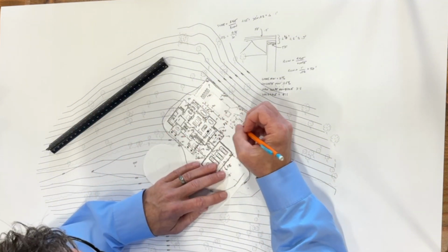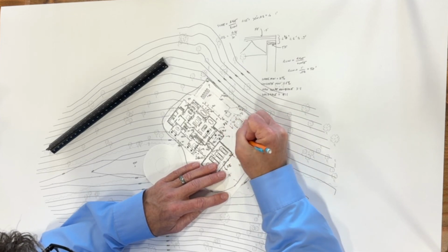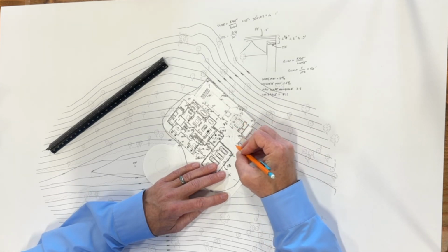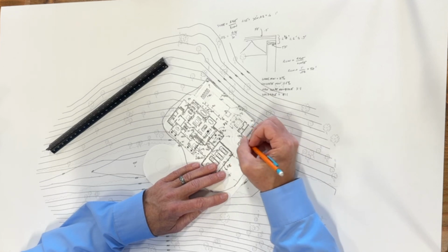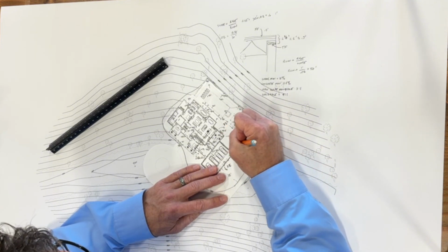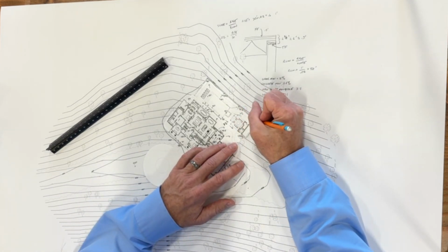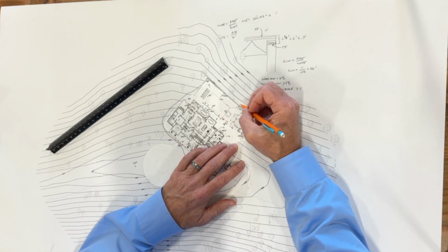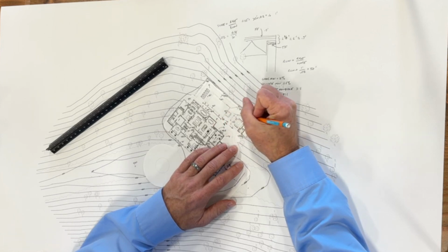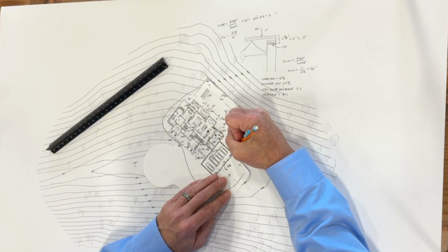So now you got to draw the 940 contour. And we could say we keep it consistent. It goes from a 941 to a 939.5. So that is a foot and a half, right? Which means the 940 should be about 2/3 of the way over. So right there is probably the 940. So that is the line there. And we want, let's see, so this is a 940 line. So that's 941, 941.5. So what that means is it's going to go something like, let's see, 941.